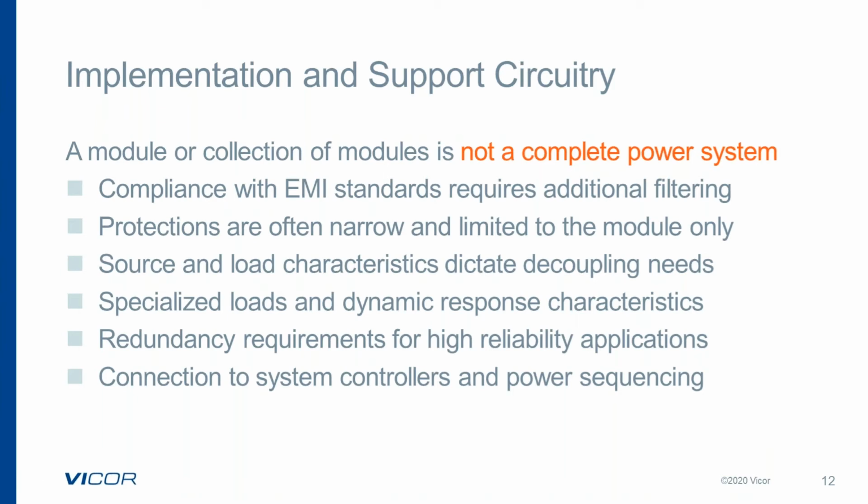In many cases, we may need support for dynamic loading in the system, whether it be a pulse load consideration. Redundancy: we need to configure the DC-to-DC converter for redundant operation, such that if one converter goes down, the system still maintains regulation.